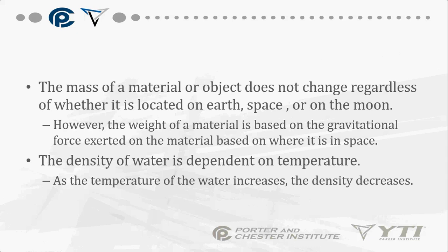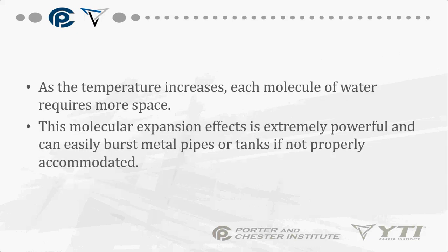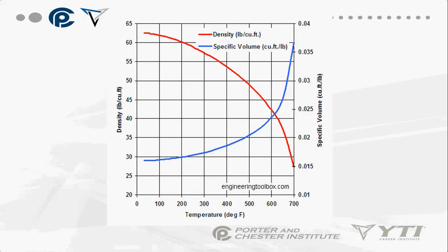But if you have a townhouse, the heat rise is much more efficient. If you have a large ranch and everything's on one floor, those circulators are going to be much more needed to get any efficiency out of that system. Again, it's not really creating any sort of pressure difference in the boiler.